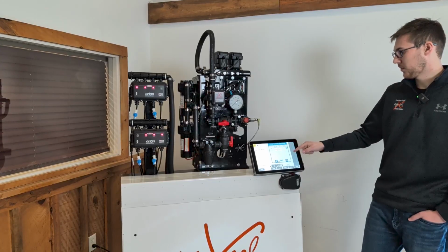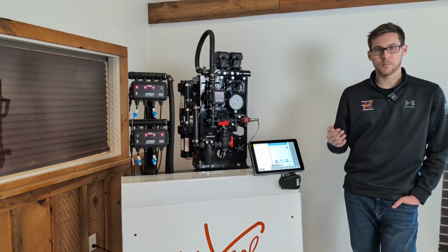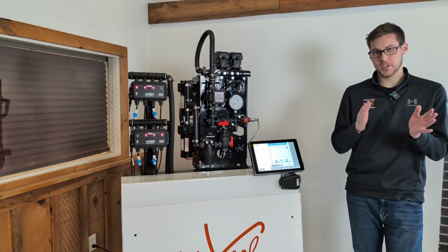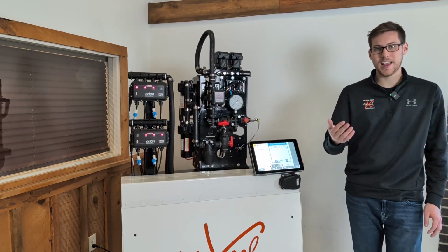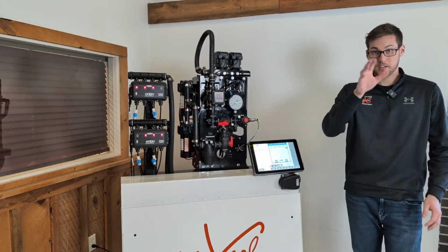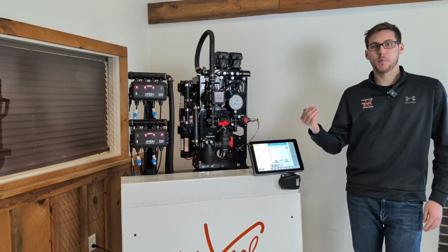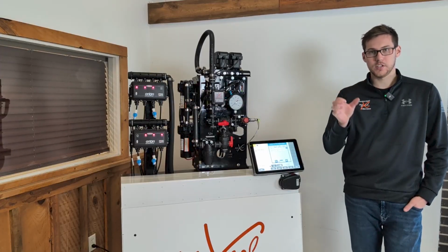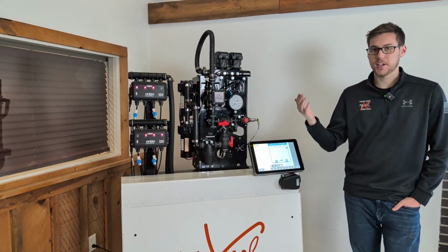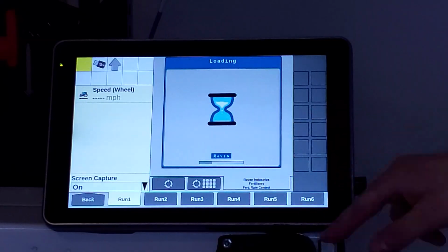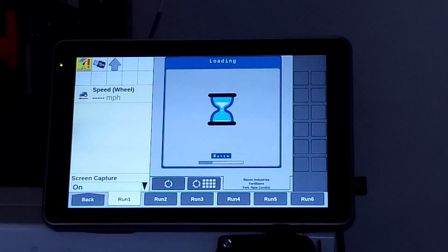You would check the equal section width box if you have an equal number of sections per product, or if the width between each section is equal. So say if you're on a stacker planter, if you have 6 rows on the bottom, 3 rows on each wing, and if that's how my sections are set up as well, then I would not check that box, and from there I can set the actual width per each section. In this case, I have 2 sections. They're both 10 foot per section, so I'll go ahead and just leave that checked. I'll press next.